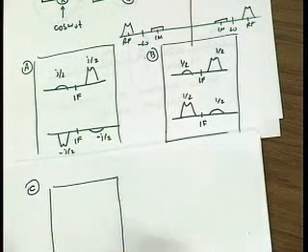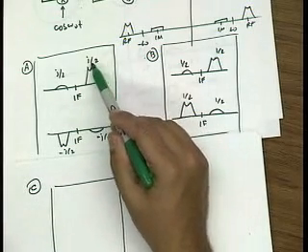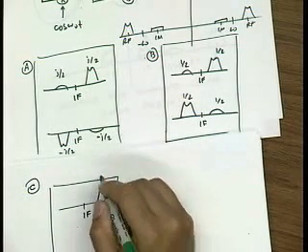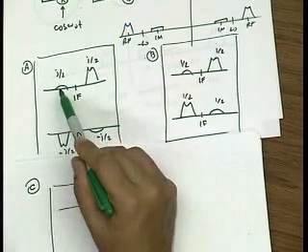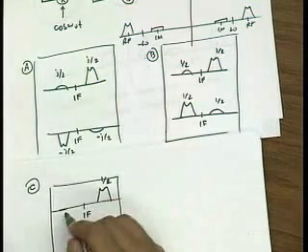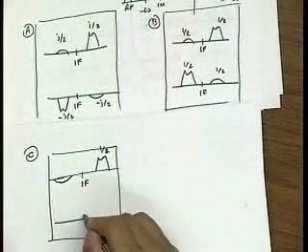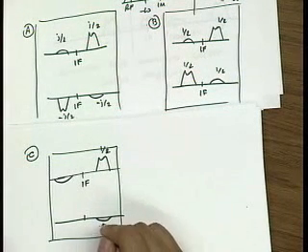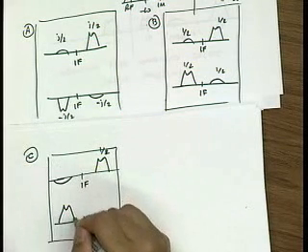Which is a shifted version of A. Okay? So when I shift this, I multiply by minus j at the positive frequencies. So this just turns into 1/2. And at the negative frequencies, I multiply by just j. So that produced j squared, minus 1, so it flips the sign. Okay? And likewise, for this spectrum here, it just comes through without a change of sign, whereas here, it flips.